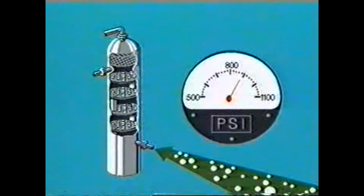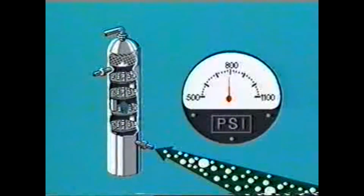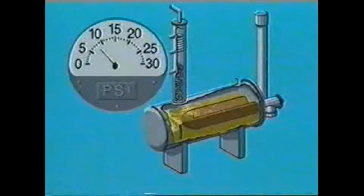Secondly, at constant gas rates, the gas velocity through the contactor increases as the pressure is decreased, causing carryover problems. Regenerator pressure will build up if there's a plugging or flooding problem in the still packing. An increase in regenerator pressure prevents some water from boiling out of the glycol, requiring higher temperatures in the reboiler. This wastes fuel gas and can lead to glycol degradation.